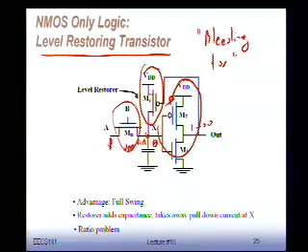Now we add another diffusion capacitance to it, plus some more gate source capacitance. So we increase the capacitance of the node to a certain extent. It's going to make it a little bit slower. It will probably impact logical effort. We expect it to do so, because larger capacitance typically doesn't bode very well in general.